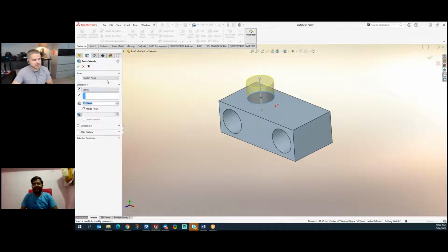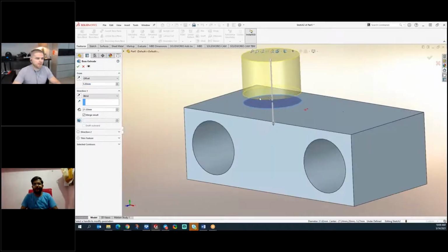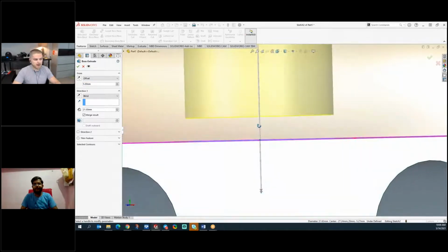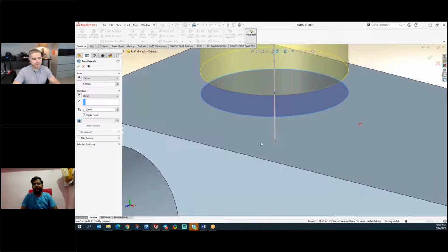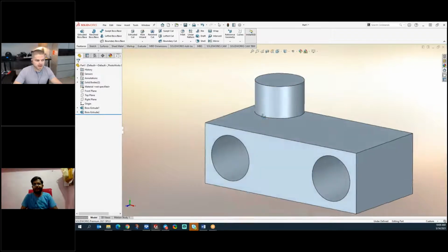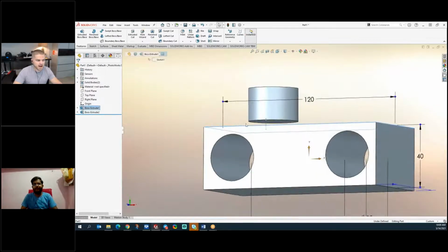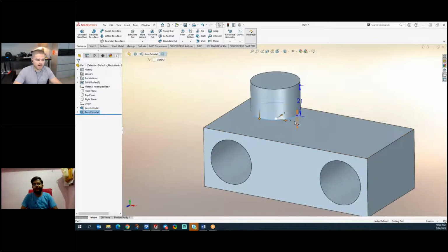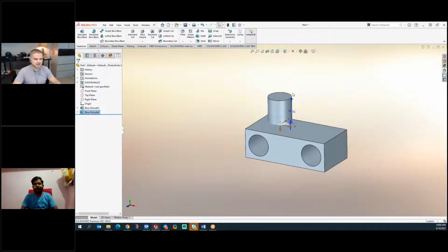You can also choose, instead of extruding from the sketch plane, to do it at an offset. So offset this by 5 millimeters or something, and then it will begin the extrusion 5 millimeters off of that face. That's powerful, because in the future, I'll hit green check here, that creates an intelligent relationship between this face and that face underneath, that no matter what, they will always have that 5mm air gap between those faces. Really, no matter how tall this part gets, we can extrude this to the moon if we want to. You'll always have that 5mm gap on that face under there.